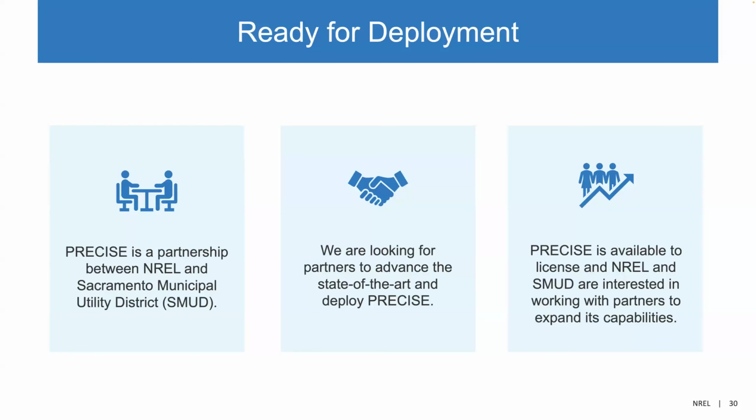The newer systems that are going in, the smart inverters, our approach right now is still first come, first served, slash, set it and forget it. So if you have an add-on system added to a system where we did not require smart inverter functions, specifically volt-var functions, but it's an add-on system being added several years after the initial system went in, we may require smart inverter functions for that added-on system. So that's where we are at with that. Hopefully that answered the question.